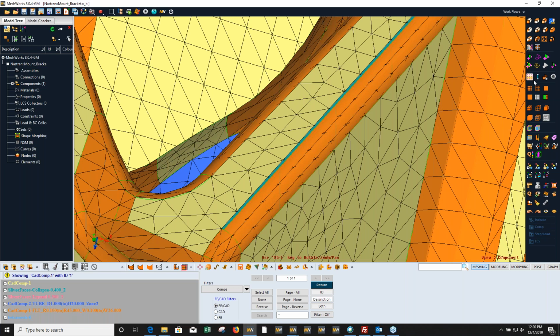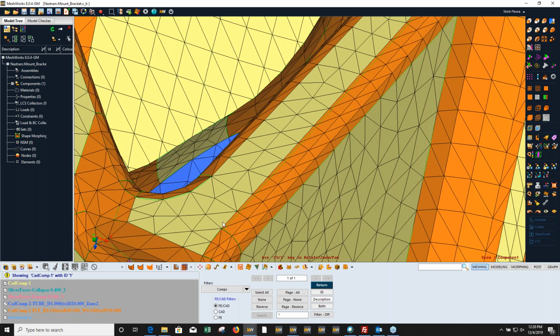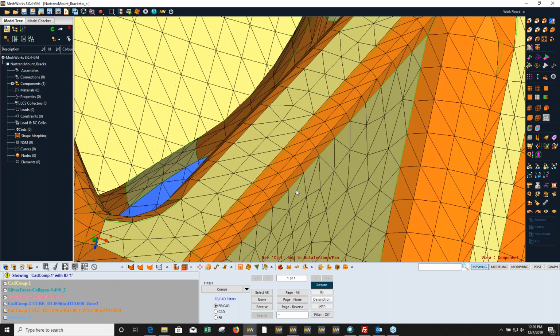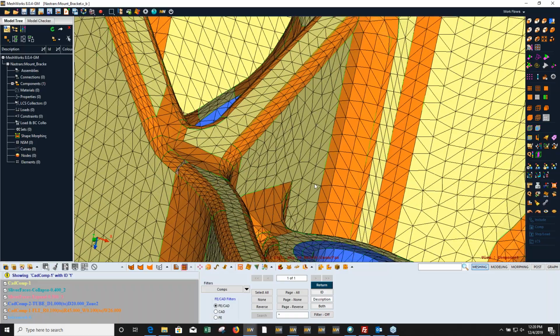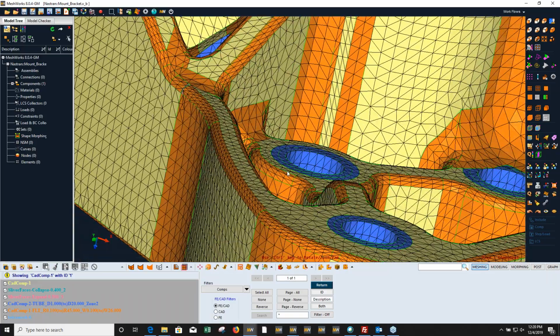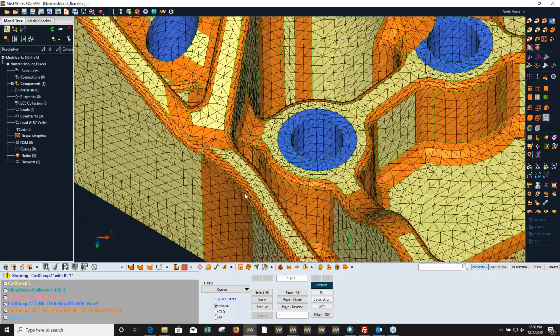So I'm going to go to the mesh view, and I'll keep the CAD in a wireframe so that you could see all the sliver surfaces have been automatically defeatured. One point I would like to add, essentially we are saying zero CAD cleanup. So you don't have to worry about any manual tinkering around.